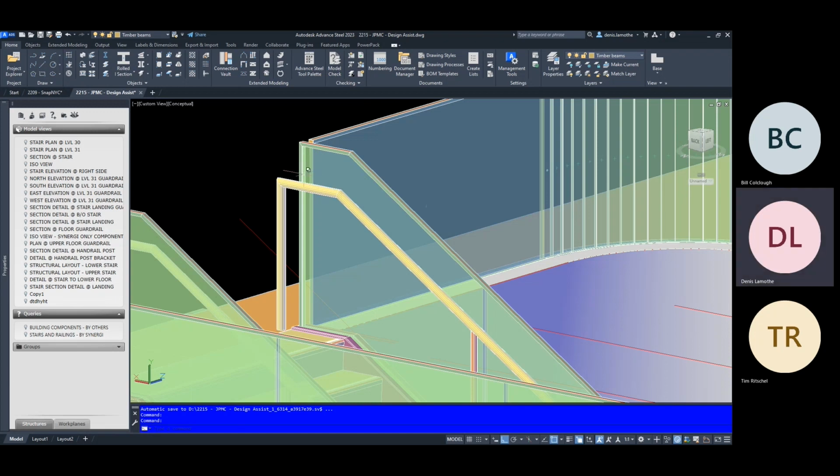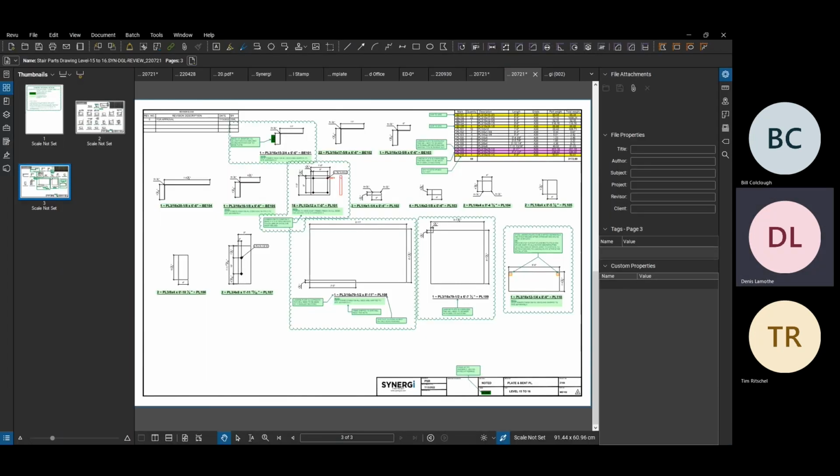And the idea behind that is we don't want someone walking with a backpack, a purse, some loose clothing, and have it snag into an open-ended handrail as they're approaching the stair and going down, and then that loop catches into the handrail, hits a bracket, and it throws them off balance and they fall. Or worst case scenario, there's a fire and you've got a fireman going up the stair with a coil of hoses wrapped around his shoulder. You don't want that hosing to get snagged in the handrail either. So we want that handrail to return to the wall or the glass as much as possible.